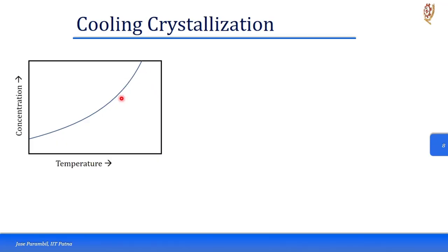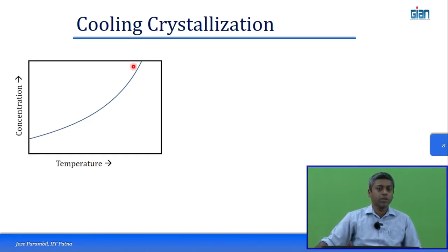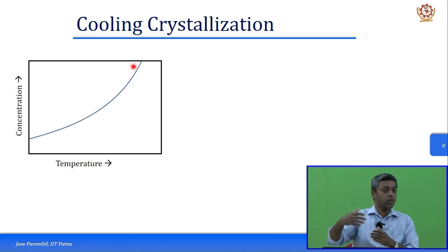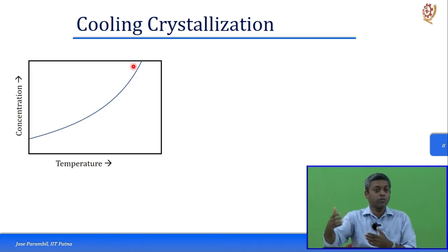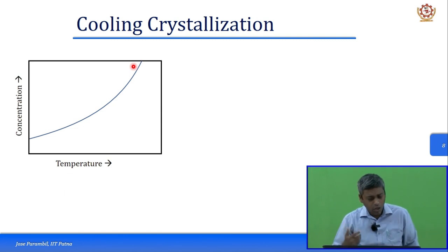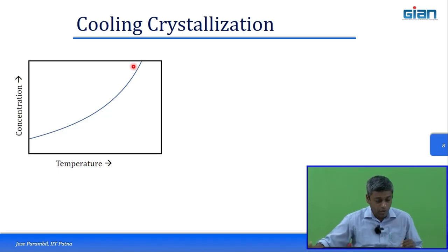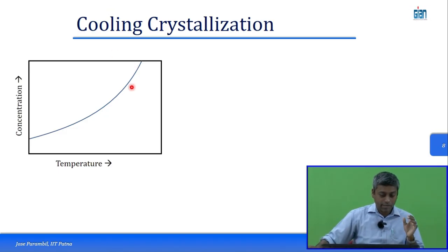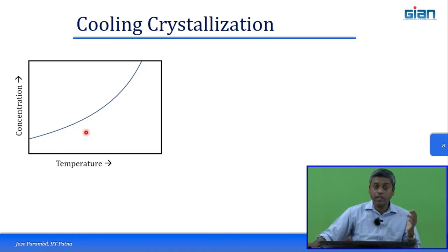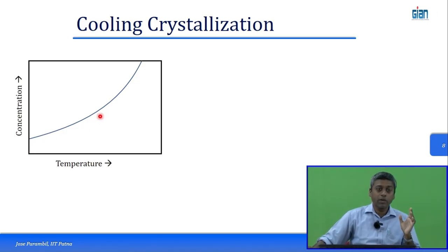So as I told you, one method for crystallization involves just cooling crystallization, where you can manipulate or play with the temperature. For example, this is the solubility line. If you consider something simple, say sugar, the more you heat, you can add more sugar into it, right? Because it would be more and more soluble at higher temperature, which is often the case for many biological systems or macromolecules as well. So typically speaking, this blue line represents the solubility. So that solubility in fact increases with temperature.